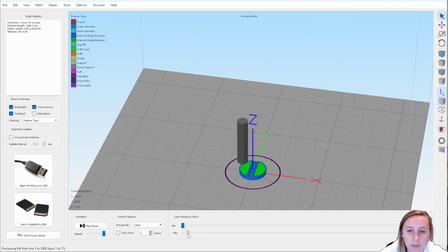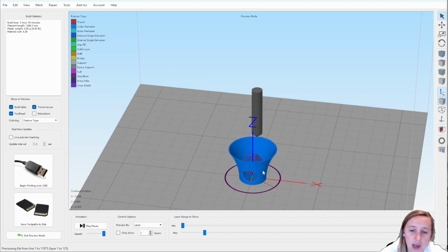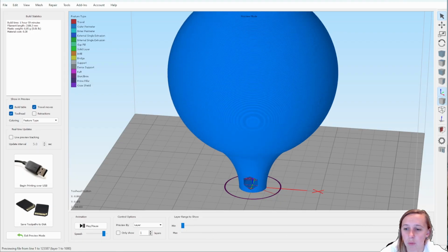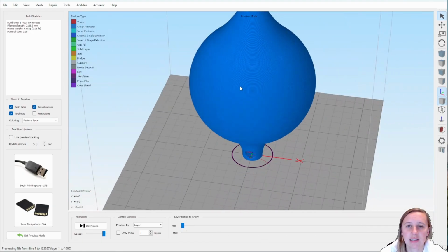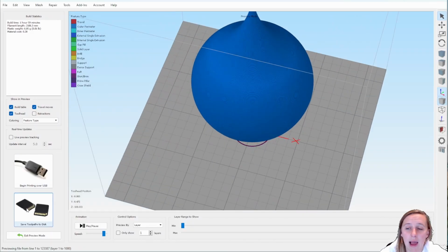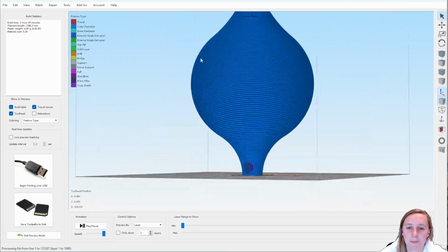So printing that up, you can print this as a solid section, and you can see there we get a solid bit for the top piece. So just keep increasing the number of bottom layers until you have that. And I actually print this one with no top layers to give a little hole in the top. Save your file and pop it on your 3D printer.